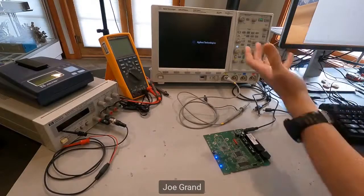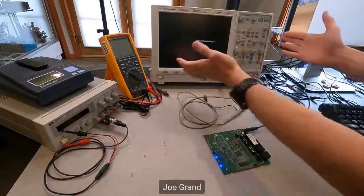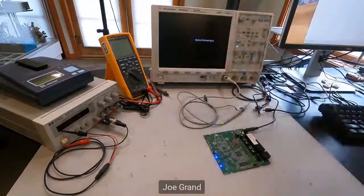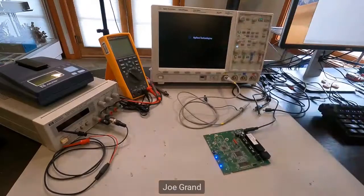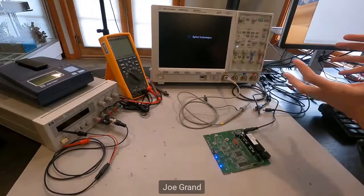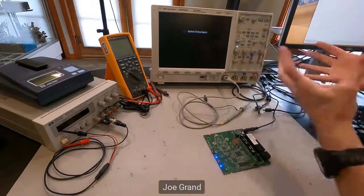The oscilloscope I'm using here is a benchtop high-end oscilloscope. It's obsolete now, but still was fairly expensive. But you don't need a super high-end tool. You can get away with a logic analyzer as well. There are a lot of open source tools, one of them is the Bus Pirate, and a lot of other very simple tools that will work with some open source logic analyzer software called Sigrok. This is just my go-to tool.